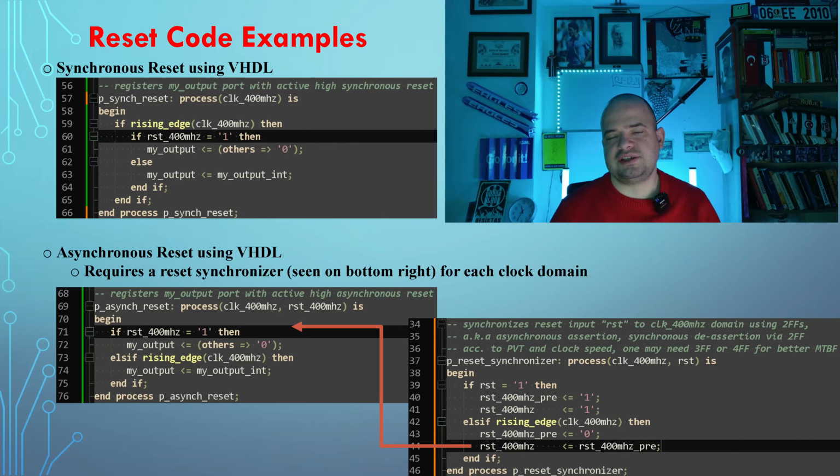So instead of resetting all, like in total 1,000 registers, you can reset just, let's say, 20 of them, and then depending on the necessities, depending on your second, third priority of resetting a signal, you may reset those in your idle state. That is a good approach, a good coding practice.